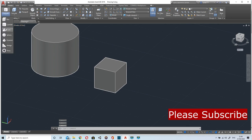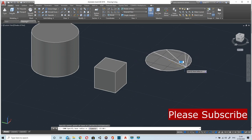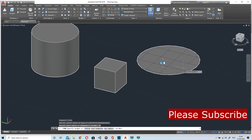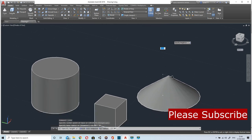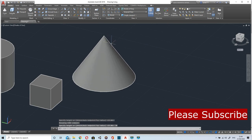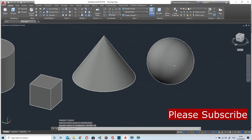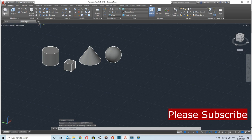Then cone. If you want to draw a cone, again it is asking for its center. I'll just pick it randomly, then radius and height. So the height is 30. After that, we have sphere. In sphere, it will only ask me the center point and radius of the sphere. So I'll just draw a sphere of 15 radius.